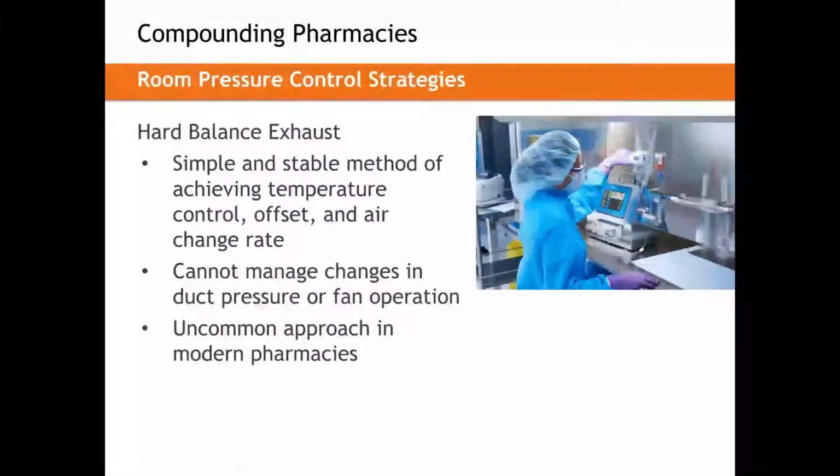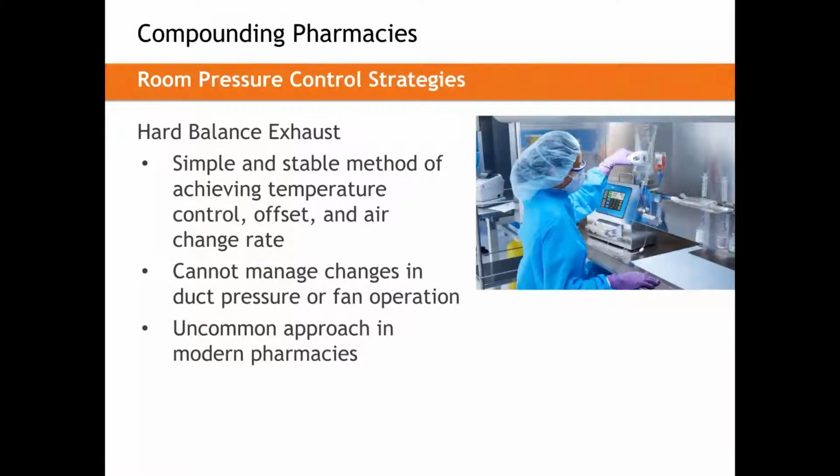There is another option available, and it is to pull out all of the airflow control valves and just do a hard balance on these spaces. This still is preferred in some markets. We do see this being used. That being said, this may work on day one, but it doesn't allow for a very dynamic system on day two. We can't manage any changes in duct static pressure without bringing in somebody to fix or rebalance that system. So it's fairly uncommon in modern pharmacies.